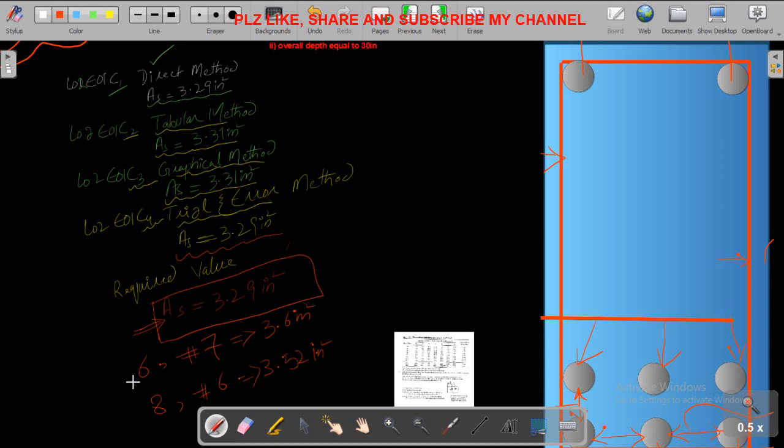In view of the spacing criteria, this selection is the best because it gives us about 2.85 inches clear spacing among the bars. Although this other one is also good because it is close to 3.29 square inches, the spacing between bars is about 1.85 inches. So we finally choose this one.